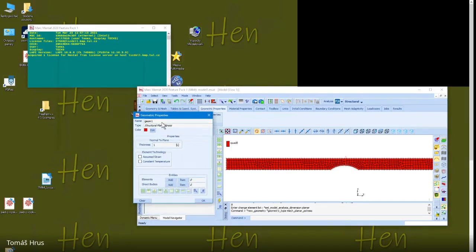and we have a new window again. Now we have to add the geometric property, and we can see the thickness. For example, 1 millimeter. And we can change the name of the geometric property. Sometimes it's much better to give a name. So I can write, for example, T for thickness. Up to you. Now we just defined the geometric property called T with value 1,